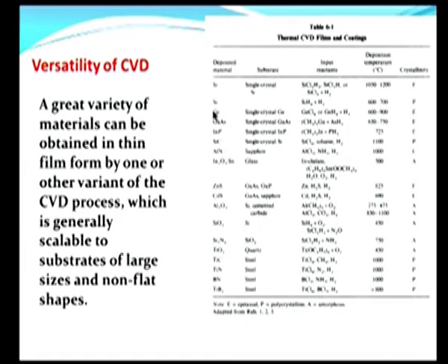For example, microcrystalline silicon is an important part of technology under development. So, it is possible to obtain by the same CVD process not only single crystal silicon as shown here, but also microcrystalline silicon by choosing the appropriate conditions. Actually, microcrystalline is generally speaking of nanocrystalline dimension, nanometric dimension. So, nanostructures of a whole host of materials can be obtained in film form by the CVD process.